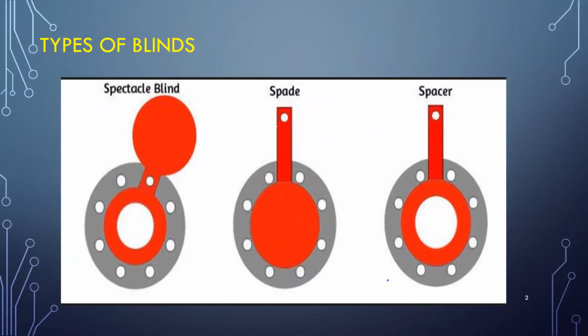In this slide, it's mainly discussing various types of blind. So here, at the left extreme, you can find the spectacle blind, or in other words, you can call it a number 8 blind. Normally the spectacle blind is mainly used on process lines, utility lines, and in addition various treatment lines. You got the point. So the spade is now used for end lines or for expansion projects.